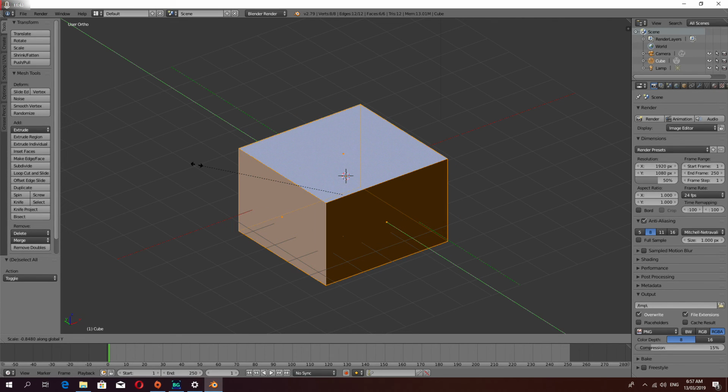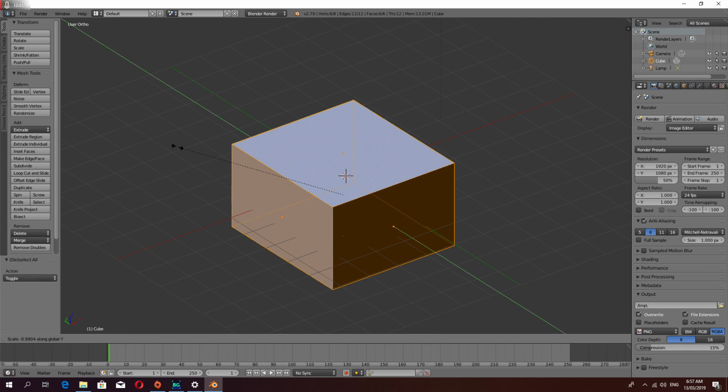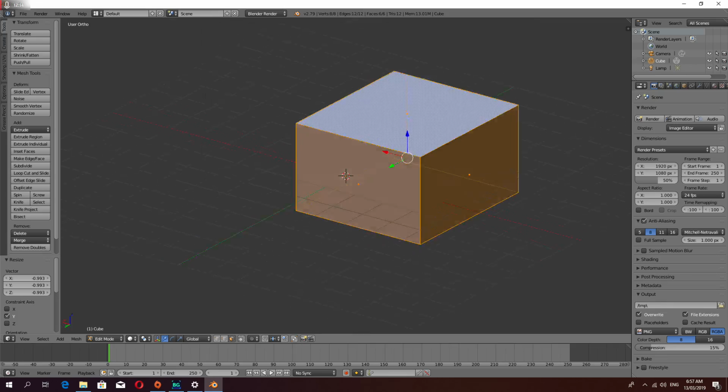It will not render properly in a proper renderer. It will not render properly in Blender if it's set up properly, because the surfaces that reflect the light or reflect that the camera can see are now inverted, and it can't actually detect that they are there. So if you were to model a whole building in something and then export it to something like Unity, you wouldn't see anything. It would be invisible unless you happen to be able to get inside it and see the faces inside it.